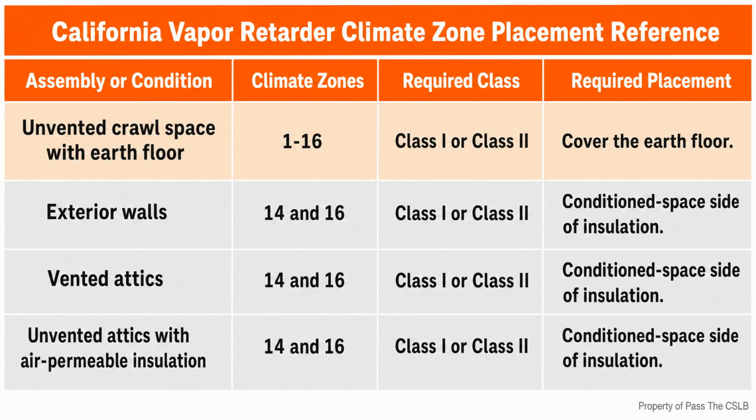Thermal bridging is another continuity problem, but it concerns heat flow through framing. Cavity insulation sits between studs. The studs themselves cross from one face of the wall toward the other and conduct heat around the cavity insulation. Continuous insulation addresses that path by extending across the framing or by being integral to the opaque envelope surface, interrupted only by necessary fasteners and service openings.